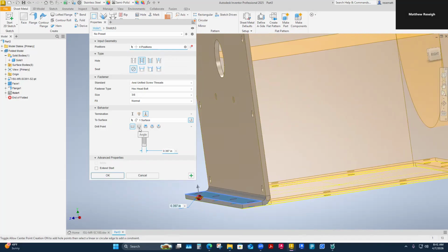Yeah, this definitely comes into play when you have what we call a blind hole, and that means my hole doesn't go all the way through, and I need to consider how the end termination is. That's a really common type of hole in the mechanical world, a blind hole, where I have to worry about how it ends and how far I can thread it. Those are really critical because generally they're threaded holes.